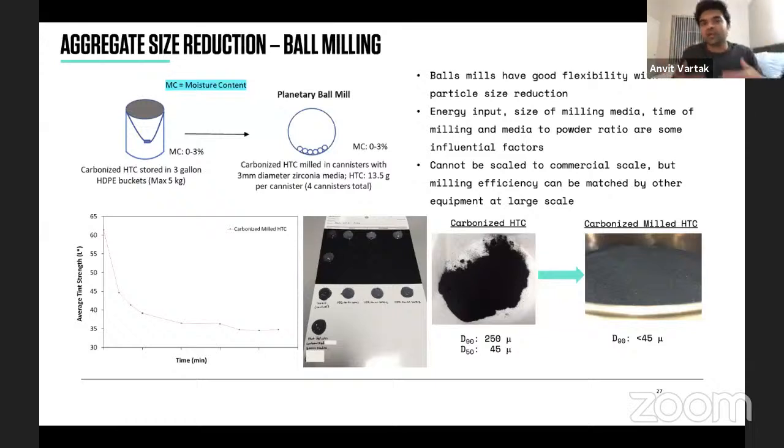I'm hoping you must have seen the ball mill. What a ball mill does is it has these media balls, metal balls, that when the mill is turning, because of the action of those media balls, when they hit, the material breaks down because of the force and momentum and hardness of those media balls. So this equipment is very helpful in breaking down the particle size.